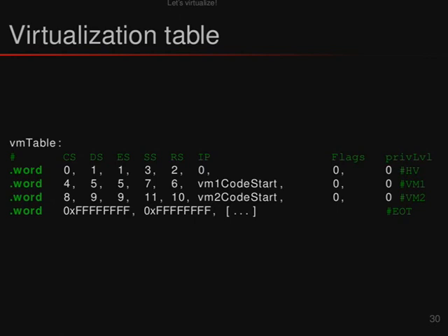Then there is a flags field, which, what does it even do? The flags field is for the flags register. It's not accessible with any instruction except those branching instructions, because if you do a compare, and you compare two numbers, several flags are set, which indicate if one of those compared numbers is lower than the other, and so on, so that you can do conditional branches.